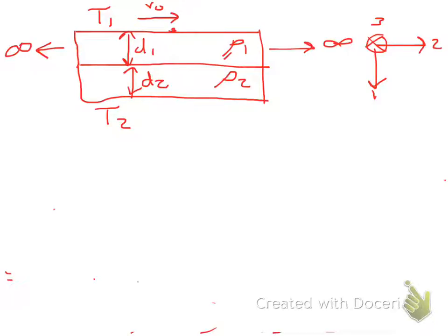So the material properties involved are density, conductivity, and specific heat. We often lump all of those together and call it the diffusivity, which is kappa. So it doesn't actually matter whether it's the density that you change or the specific heat or any change in these two materials, you would be changing its thermal properties. And how did that change our solution on Tuesday? They made the lines go from vertical to having a slope.